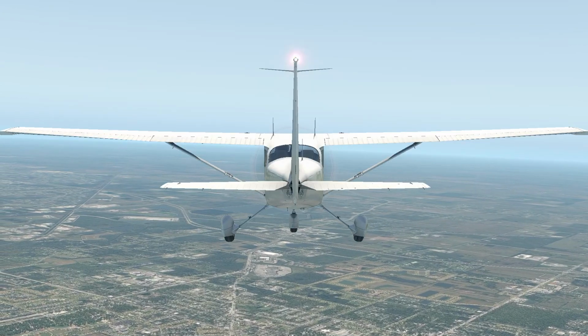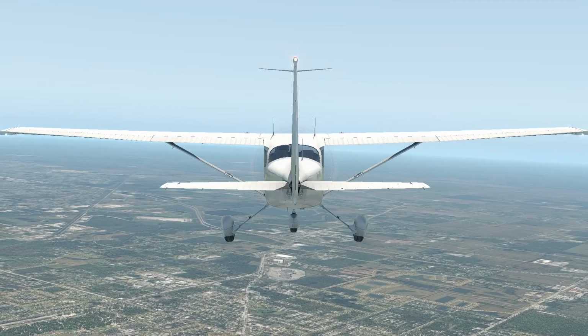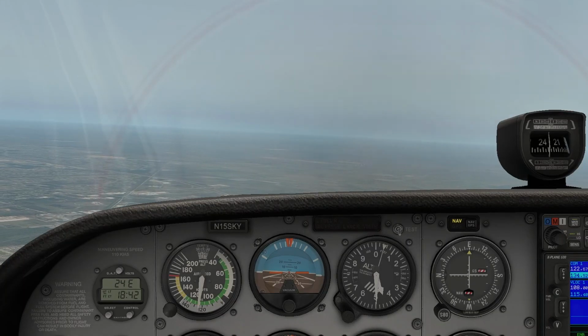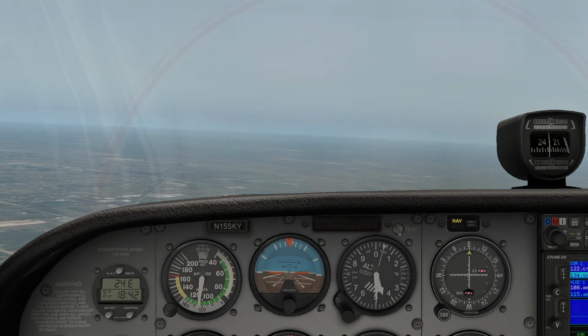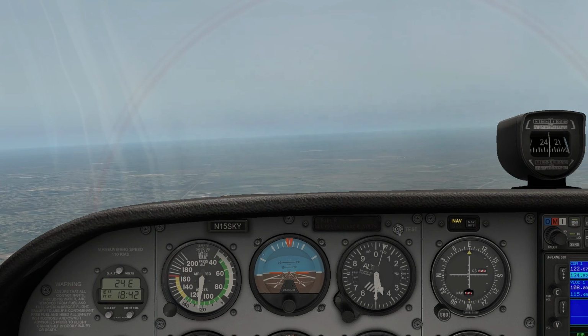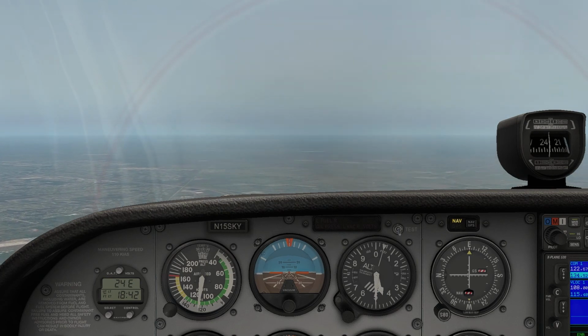Due to these tendencies, your airplane will slightly and slowly roll to the left during flight. Since you cannot feel this roll, you need to be aware of your airplane's attitude and make the frequent but slight adjustment to remain level. It literally is a slight tipping of the wing to the right.